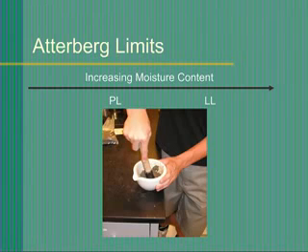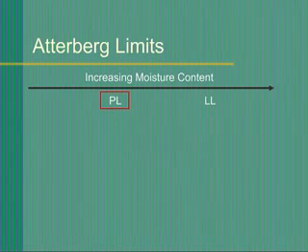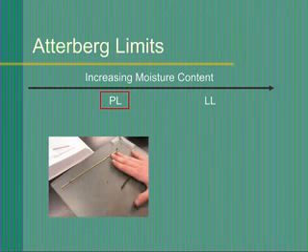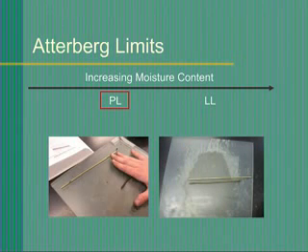If the soil being tested contains little or no material coarser than a number 40 sieve, you can skip this pulverizing and sieving procedure. The plastic limit test procedure involves taking a sample of soil slightly wetter than the plastic limit and carefully rolling the soil sample into a thread 1/8 of an inch in diameter, as shown. So long as the soil can be rolled into a 1/8 inch diameter rod without falling apart, the soil is wetter than the plastic limit.